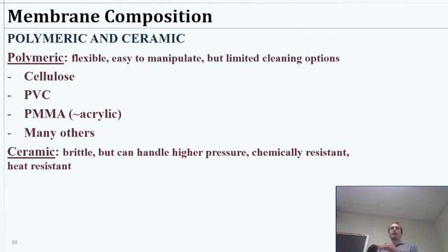You can shape it how you like it, and then you fire it. And then based on that clay structure and the air pockets and everything that form, you have a pretty solid structure that's resistant. It's not going to dissolve, which is really important, right? That's part of the firing process. But if you carefully design that, then you can use those pores as a membrane.